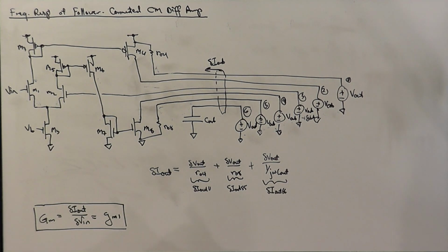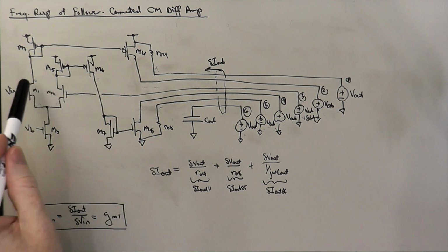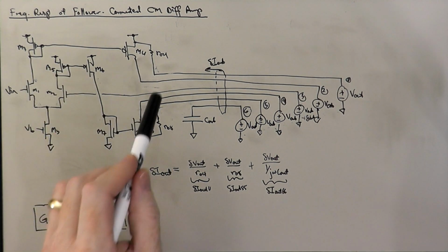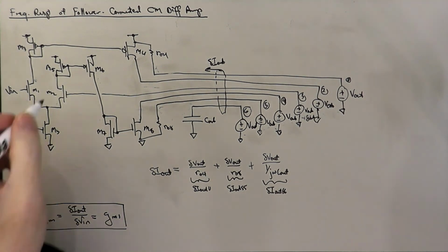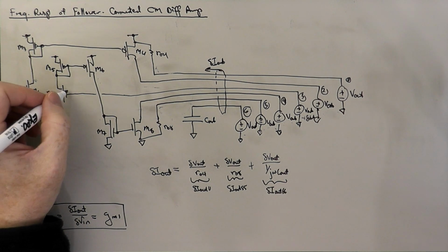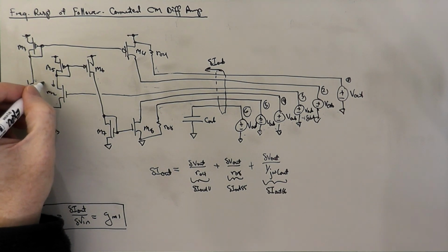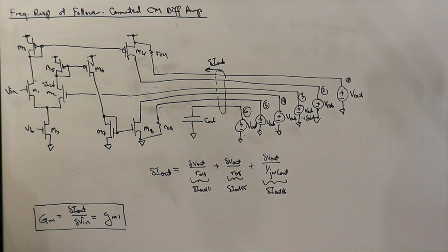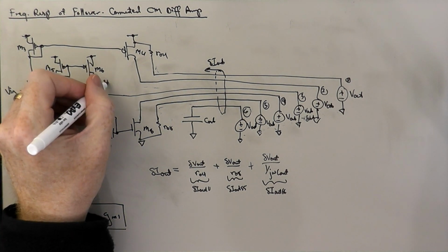Okay, only now we've split the source, and the two sort of different effects as we go around different pathways in the circuit are going to come out in different branches. Okay, so we're increasing the current in M2. So there's a delta I2. Okay, and that's going to do 2 things. It's going to be mirrored by M5, M6, delta I2.